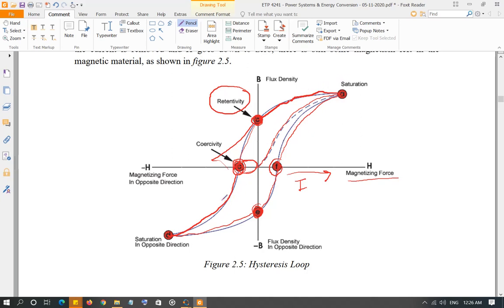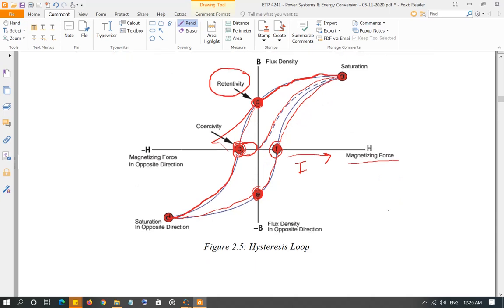And you're going to study the hysteresis loop here, and also in linear integrated circuits when we discuss comparators. But this is the hysteresis loop. And this phenomenon is called hysteresis, where you basically need some energy to set up the dipoles, and if you remove that energy, your dipoles are not totally misaligned. Then you provide energy in the opposite direction to misalign all the dipoles. Keep going in the opposite direction, eventually it's going to saturate again, and so on and so forth. So this phenomenon is called hysteresis, and the loop is called the hysteresis loop.